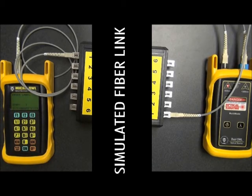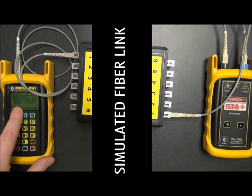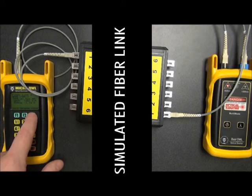So once you're done entering your label, you press done, and you see a review of the information on the screen. So you have fiber link 1, that's your link name. You have your fiber ID, fiber:1, your fiber type, and your wavelength, and your loss, and your pass-fail result. Okay, if you're satisfied with this result, we simply press the F3 button for save.